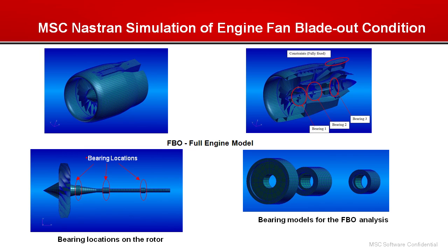The fan blade out model has about 9,000 nodes and about 8,000 shell elements, and is deemed to be sufficiently detailed to capture the physics of the problem. Again, this is only a simple example to make sure that we can include that as part of our tutorials and documentation. We didn't want to construct a 4 million element model here.